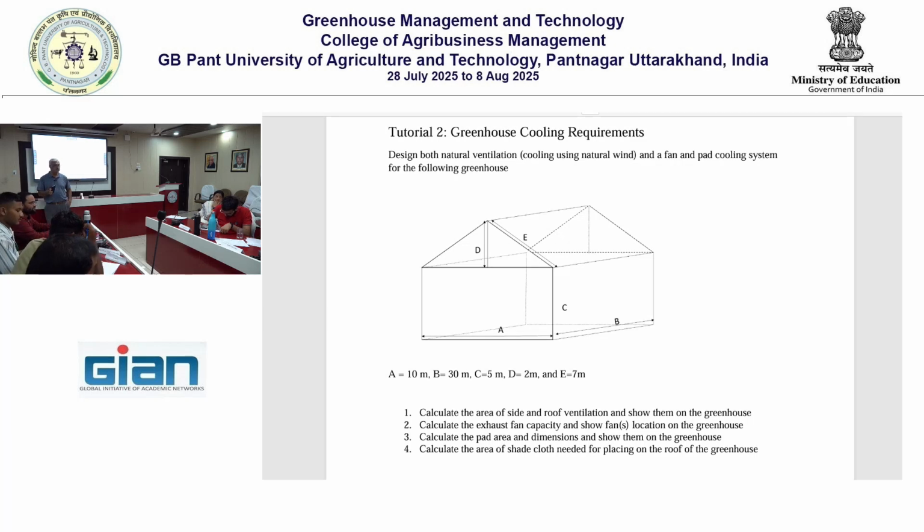So what is the optimal place to place those cooling pads? Like, it has to be closer to the ground, or if we have got the area, we can put it a bit in the center. The cooling pad should be at the height of the fans, right? If the fans are here and the pads are there, oh no, they should be similar. And you don't put the fans at ground level. So ideal would be approximately you leave 5 feet from the ground and then put your fans there. Same with the cooling pads too, about 5 feet. Okay. Yeah, a good question. I didn't cover that when I was teaching.